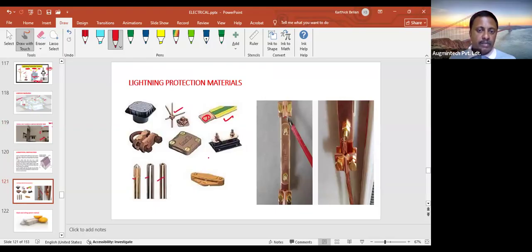These are the earth rods. And this is a square clamp, which we use for different connections of your down conductor. Like we are bonding it to the metallic equipment also, like AHUs or whatever it may be, all mechanical equipment. So we need this square clamp for bonding purposes, and a rod to tape clamp. We have this tape clamp also finally while earthing it.